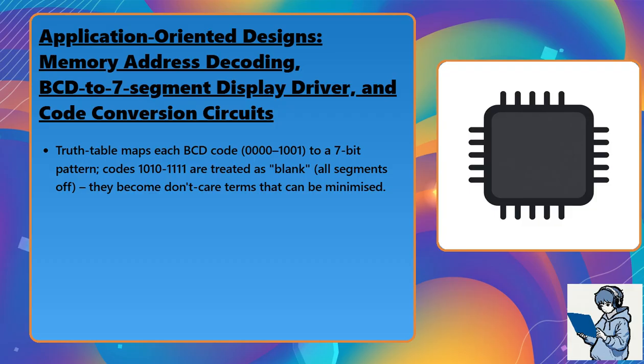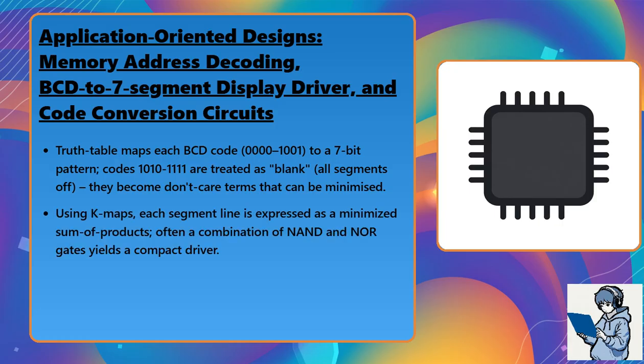Codes 1010 to 1111 are treated as blank. All segments off, they become don't care terms that can be minimized. Using K-maps, each segment line is expressed as a minimized sum of products. Often a combination of NAND and NOR gates yields a compact driver.